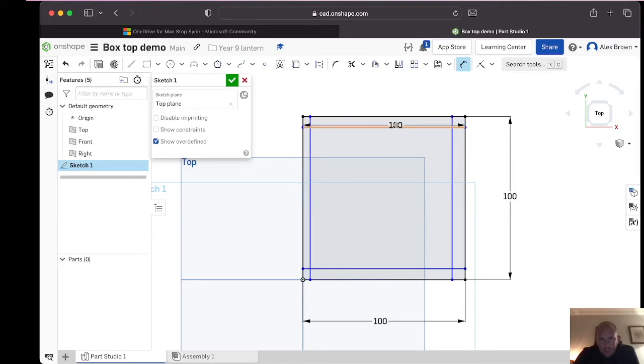But what I want to do is go up, but before I click it again, I want to go up so it highlights the line above it. So it's gone yellow there. Click it again, and this time it changes. So I'm actually dimensioning the distance between those 2 lines. So bring it out to where it's convenient, out of the way, click it, and I'm just going to type 4, because that's the distance I want it to be, 4mm.